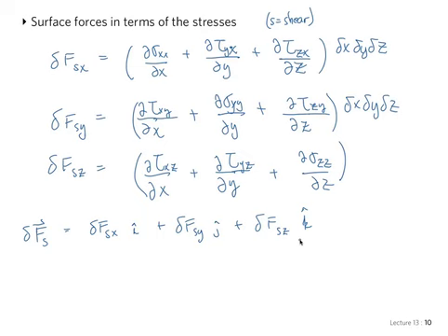The acceleration we already calculated in the beginning of the lecture, and when we multiply by the mass, it is rho times the volume. And you can see, I've forgotten the volume, that volume is going to cancel out from the whole equation because I have volume here and on the left. So now what we're going to do is force equals mass times acceleration for a small element. This mass is rho dx, dy, dz. The acceleration we already calculated before, so we're going to be able to write it immediately.